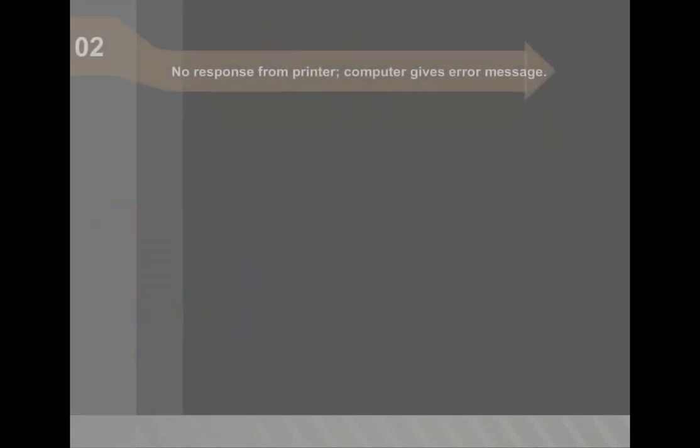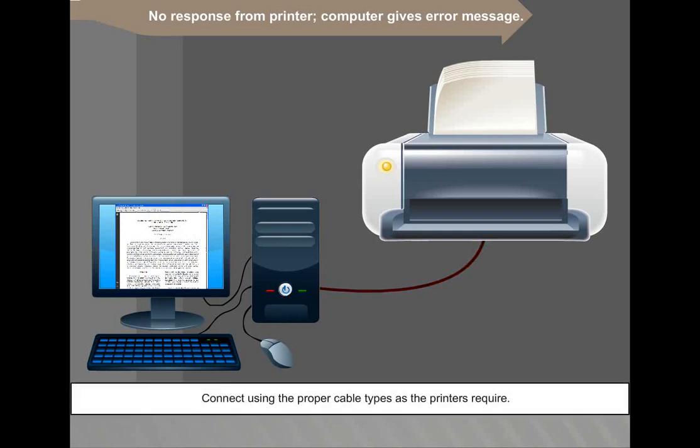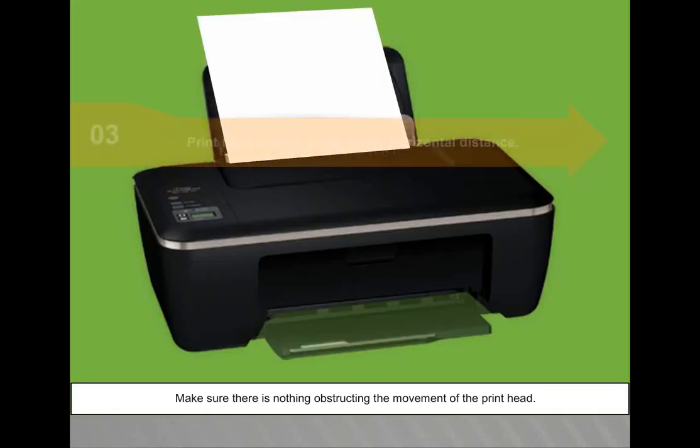No response from printer, computer gives error message. Check for the proper connection of cables and look for an online or select button to press on the printer. Connect using the proper cable types as the printers require.